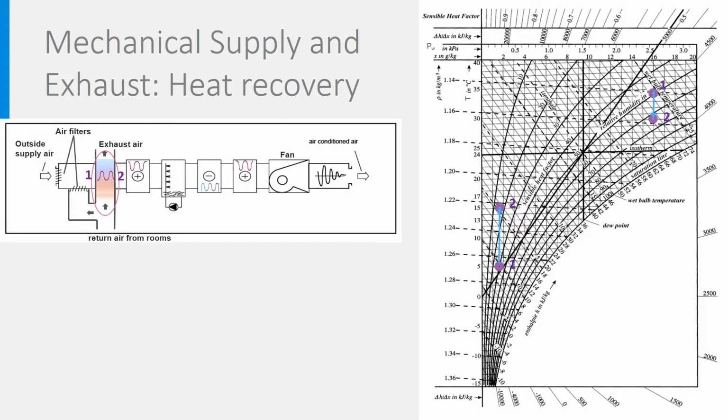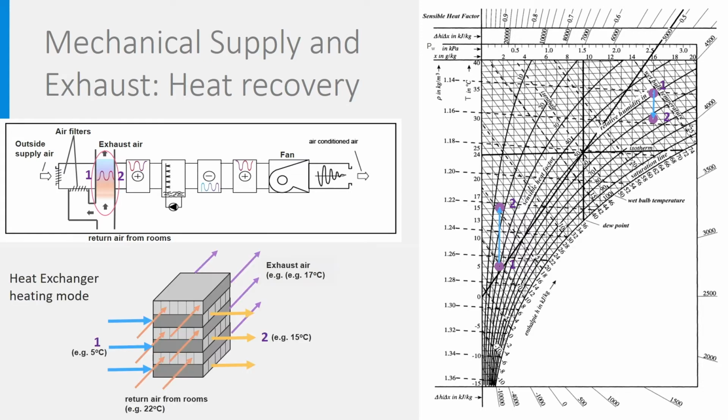In such a heat exchanger, the supply air and the return air are not in contact. There is only heat exchange, no mixing. This is therefore much cleaner. The supply air cannot be polluted by the return one. Such a heat exchanger could look like this cross-flow heat exchanger.